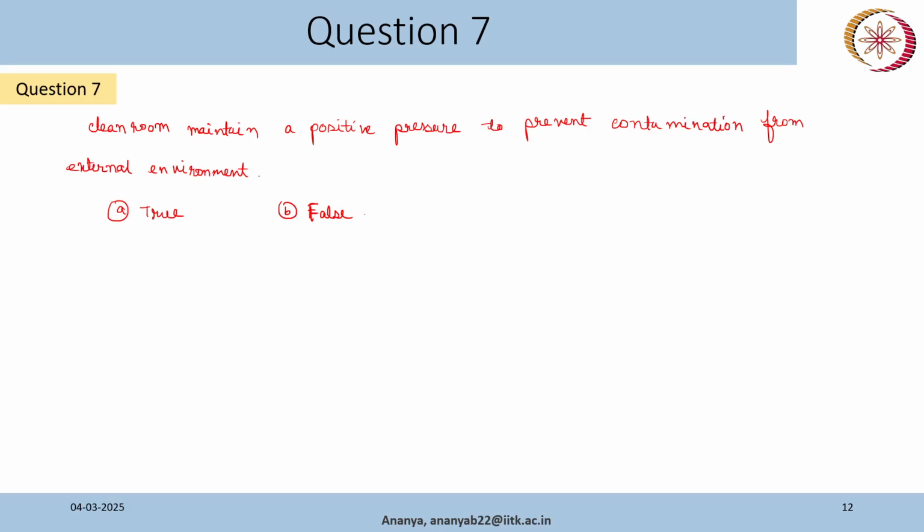And one thing we should also keep in mind while maintaining it is that the clean room should have a positive pressure to prevent contamination from the external environment.